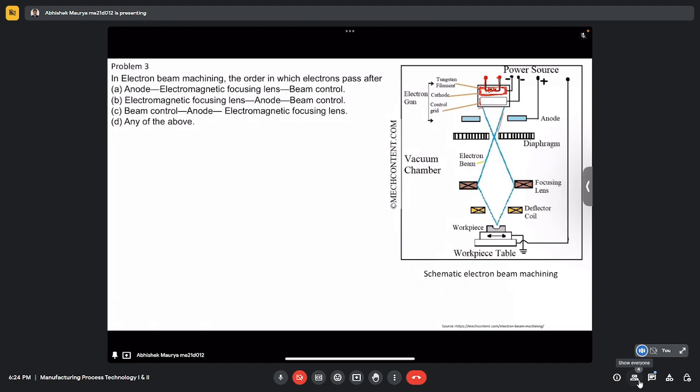towards the bottom direction. And after that we have the anode, and you can see there is a potential difference between this anode and this cathode. Because of this potential difference, whatever electrons are emitted from the surface of the cathode because of thermionic emission get accelerated. So those electrons get accelerated according to the field, so here it is towards the bottom direction.